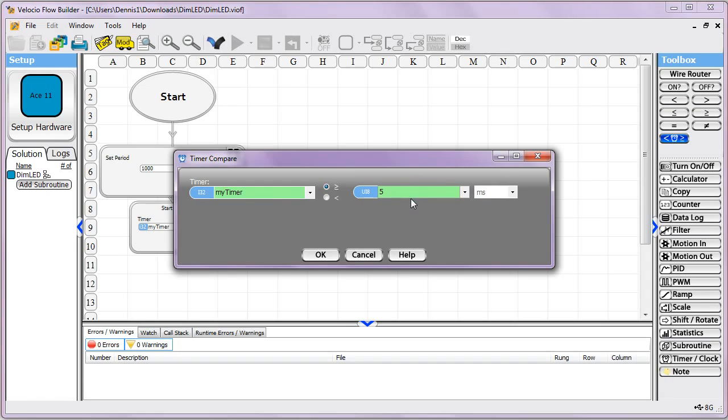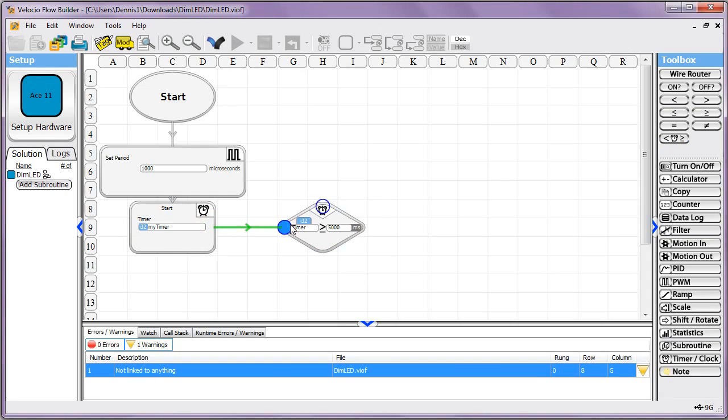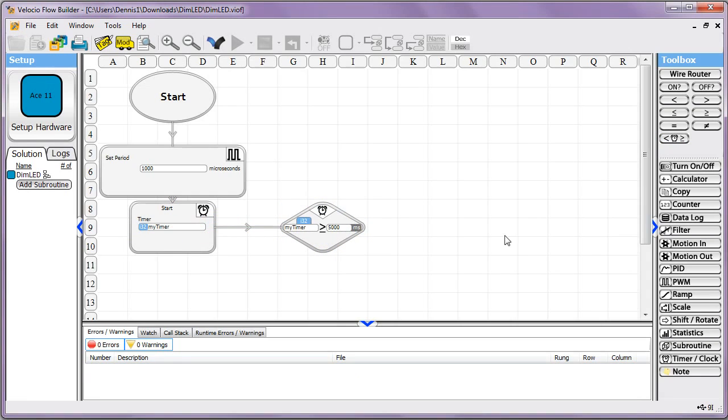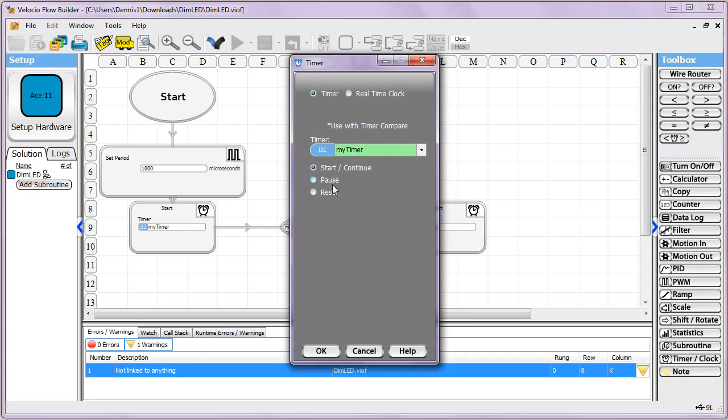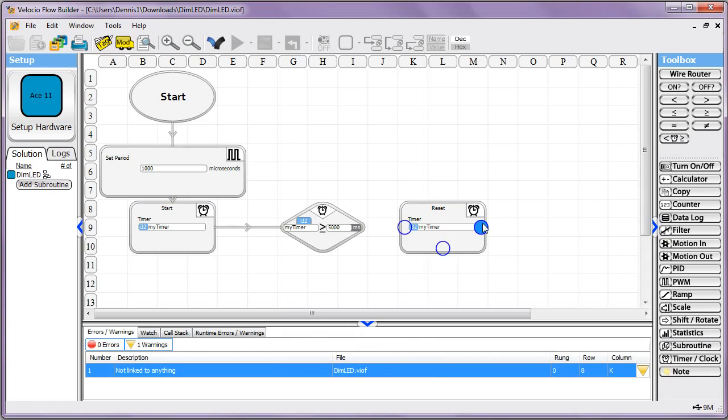and we'll do it in this just to make it real understandable. The timer by default is, if you looked at the raw data, if you took the tag and you made a comparison in another function, you'd see that it's recorded in milliseconds. So we'll see if it's greater than or equal to 5,000 milliseconds, and if it is, I'll just do a Control-C copy of this, and we'll reset the timer and leave it back there.